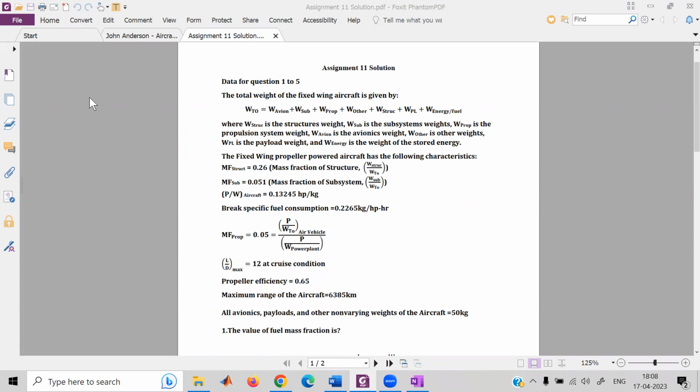My idea in asking this question is, let's think we want to design an aircraft. If you think about design philosophy, these mass fractions are usually known to us. For example, when we want to design an aircraft, we have in mind an aircraft that is almost similar to the one we want. So we can look at the historical data and find out what the structural mass fraction should be. So the numbers given in this question are usually known to us.